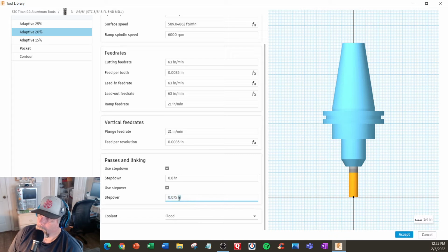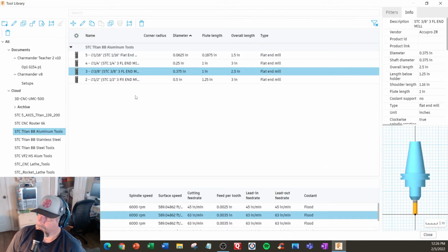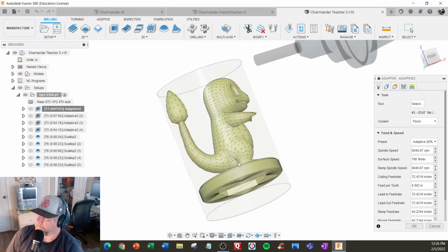So in here, if I double click on this, I originally had the library linked to, I'll just show you for a second, tool underscore diameter. Oops, sorry, I forgot to spell it right. And you can't use capital T, I found that out. Times, let's see, that'd be 0.2. So that'd be our step over. If I actually end up copying the tool, I really don't have to change a lot of data. So hit accept, and that gives me 75 thousandths. Or you can plug in hard numbers, but I'm trying to use the parameters more.